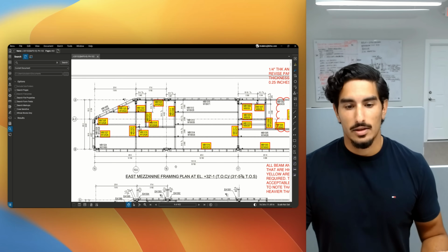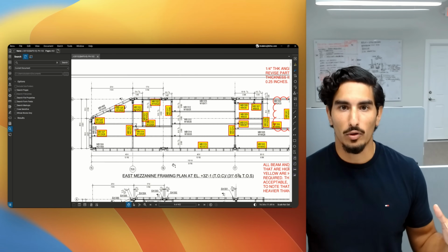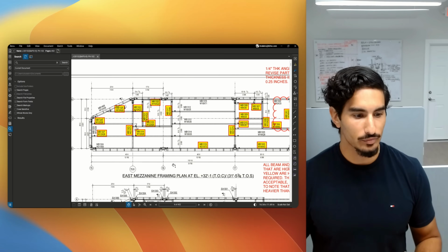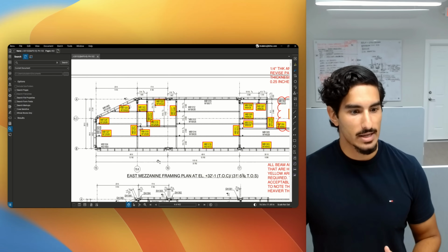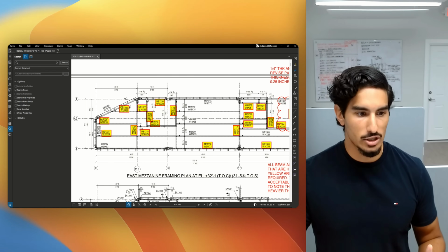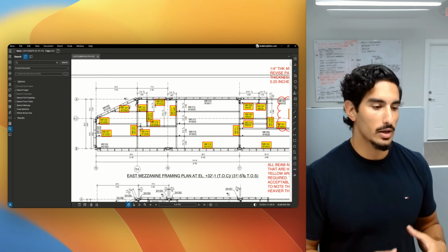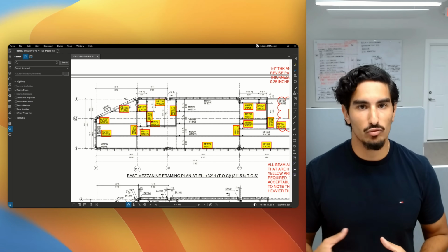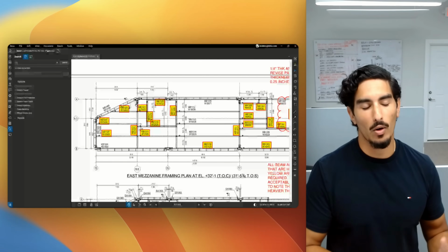And this is a simple example. This is the mezzanine level. This isn't even the full bay or all the full structures, but I thought this was a good sample size to really run this experiment against. So what we're looking at right now is just the on-plan framing section. And typically what we would do is we would go through each connection and we would find the different piece mark drawings. So you get a column piece mark or a beam piece mark, and you'd slowly work your way and read your way through the drawings to get all of the variables that you needed before.